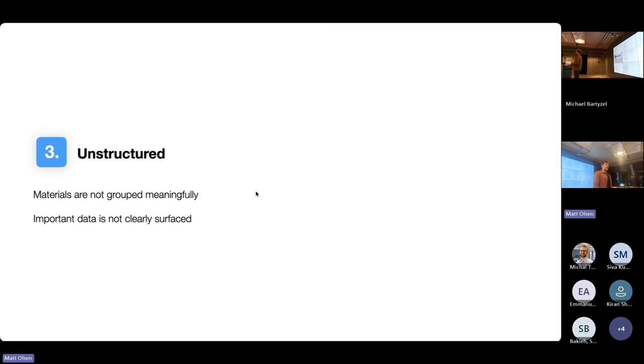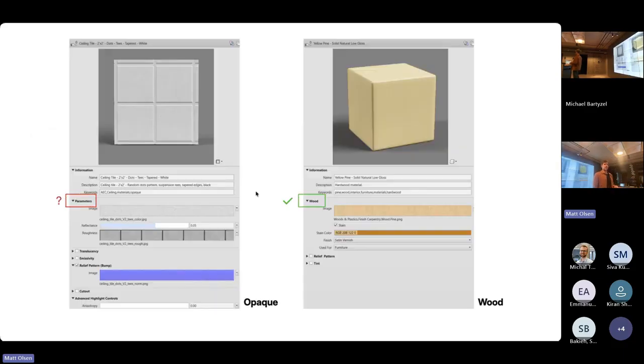Also, while the Revit material browser gives you a lot of information, sometimes the more important information isn't presented in the most clear way. For instance, the appearance asset types I mentioned earlier, they very much drive the visual properties that are available for the material, but the type you're using is frequently missed, even by those that are experienced in creating materials.